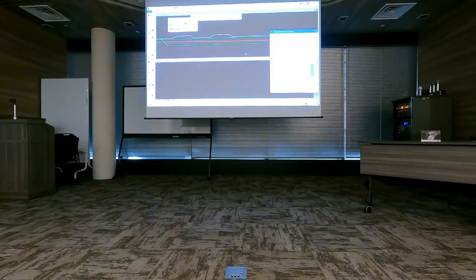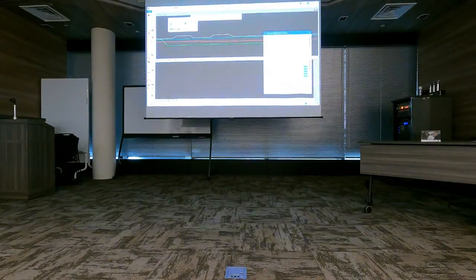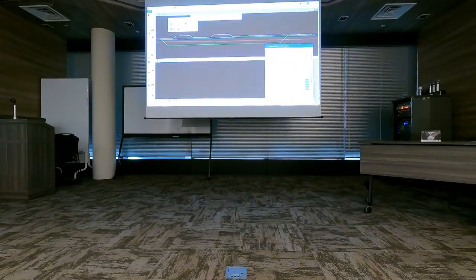And with compute multiple surface volume, the computation principle is the same, that the software uses a grid approach, computes the elevation difference of surfaces at one xy location at the time. Even with multiple TIN models, it calculates using the same grid method.